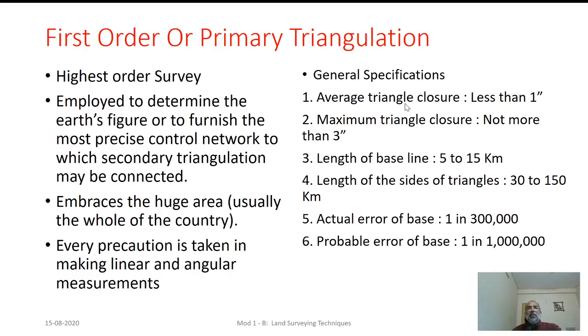After carrying out the computations, it is expected to have the average triangular closure less than 1 second. Let me remind you, as we are dealing with first order or primary triangulation, the kind of triangle we will be dealing with won't be a plane one, it will be a spherical triangle.